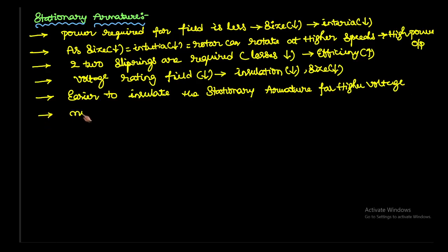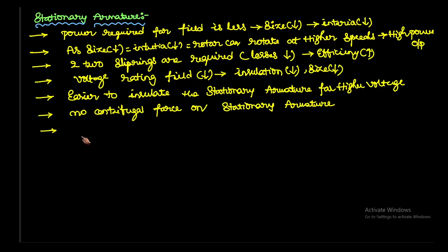Next we will see another advantage. There is no centrifugal force on the stationary armature, because there is no rotation. Cooling is easy; cooling can be provided very easily because of the stationary armature.